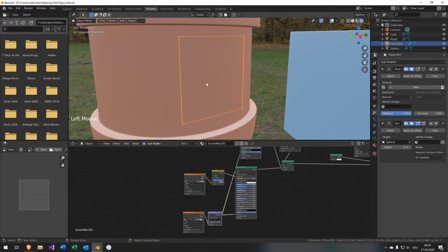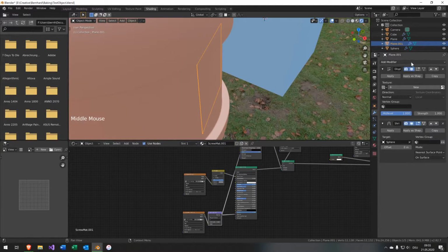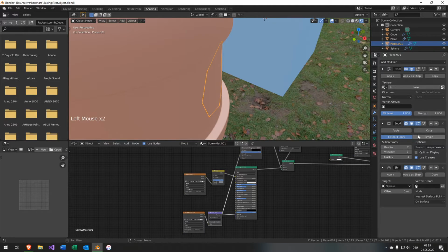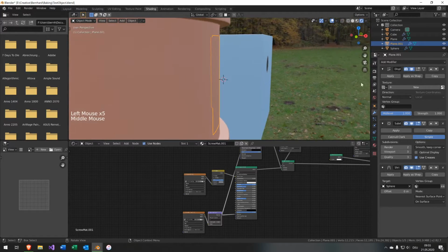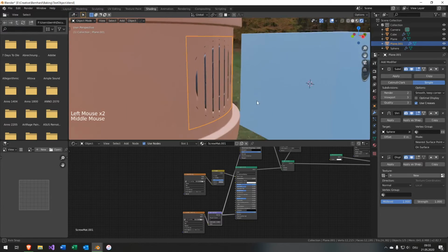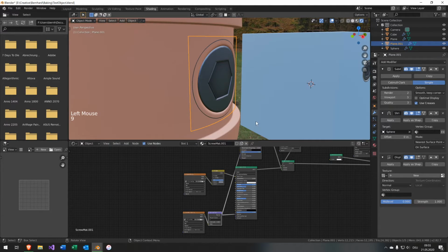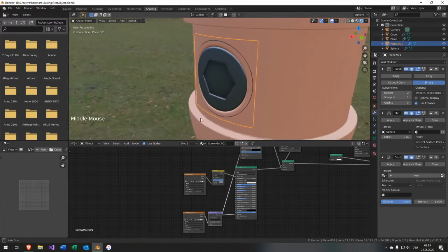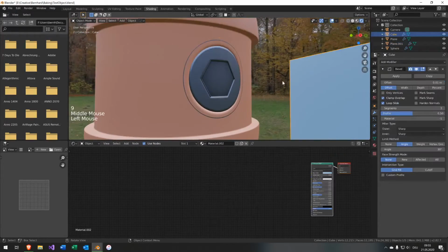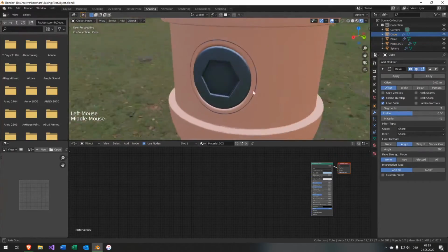So we're selecting our cylinder and now it's gone. This is due to the fact that we need to subdivide our geometry, because the shrink wrap is actually using the geometry of our plane and it wasn't subdivided enough in order to shrink wrap it. I'm gonna change the mid-level of the displace modifier. Maybe it's a bit far from the surface, but it's just some kind of playing around with the values until you wrap it around.